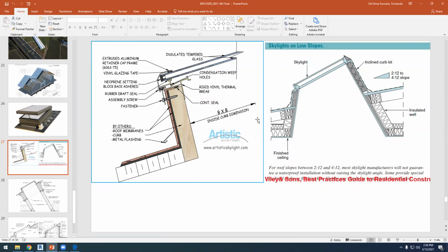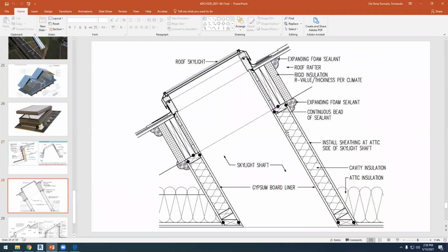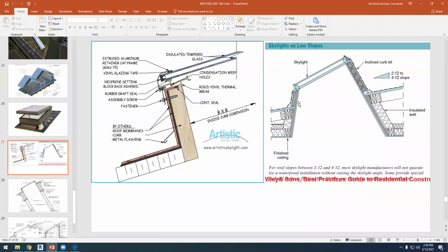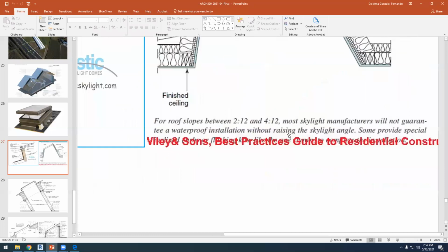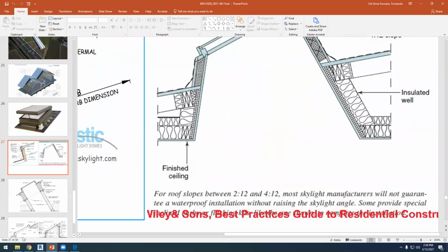And what is this? Well, basically, what do we have to do? We have thermal insulation, and then we have structural wood elements. And then we need a waterproof layer as well, and the roofing material, which is going to be this metal, this zinc that we use. But it's made of wood, so we have 2 layers of wood. We have rigid insulation there, and then we need to fill. Okay, so we need to fill everything with thermal insulation.